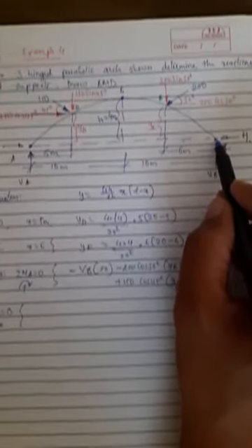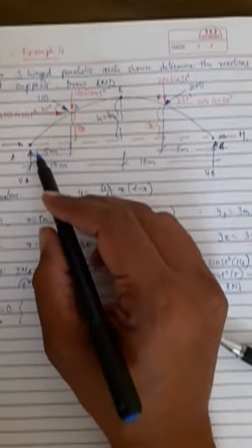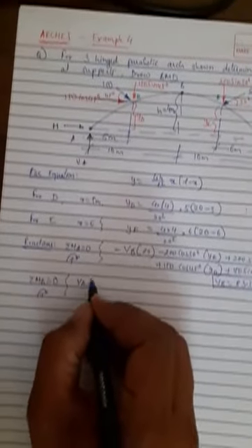Okay, now let's write the equation for moments about B is equal to 0. Again, clockwise moments will be considered positive. Keep your finger at B and start analyzing from A, considering all the forces from A till point B. First consider VA into perpendicular distance 20.